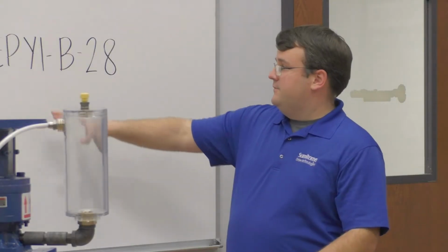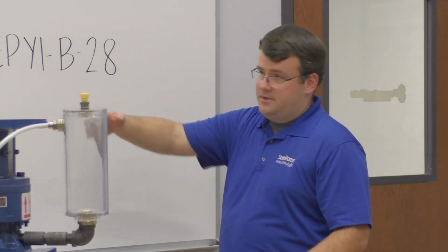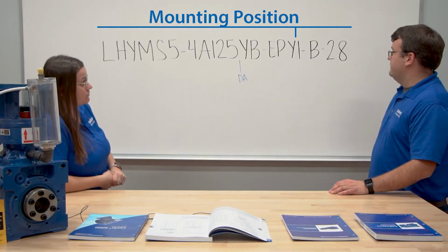If you order as a Y1 and you mount it like a Y2, you're missing a whole lot of oil. So we have to make sure that's covered early on in the installation or selection process. Definitely keep an eye out for that one as well. In certain ones, it can change parts, and some of them will change to being grease lubricated in some areas to help.